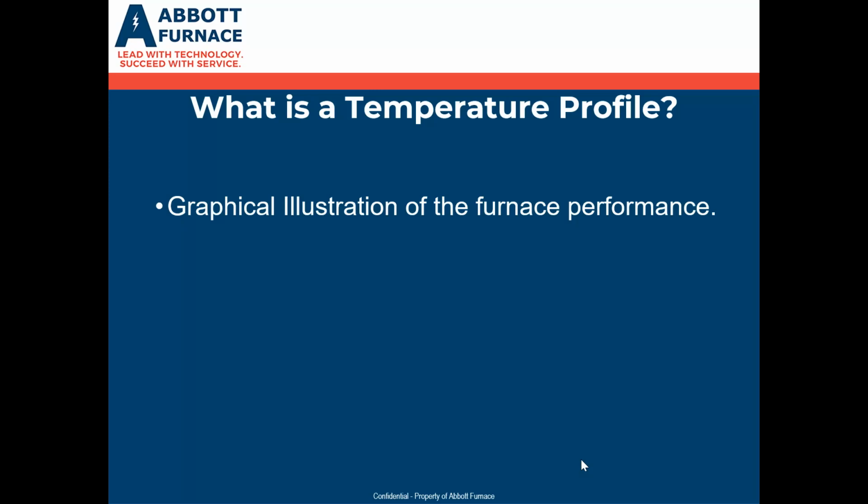I'll turn it over to Dean, and he'll talk a little bit about temperature profiles. Morning, everyone. So, a temperature profile, or what they call them nowadays, is a TUS, which is a temperature uniformity survey. We run thermocouples down through the center of the furnace, and it'll graph out on whatever kind of data recorder you're using, the temperatures as it goes down through there.